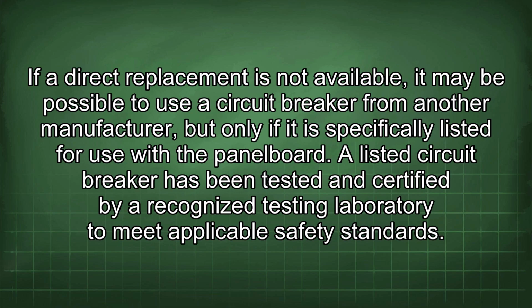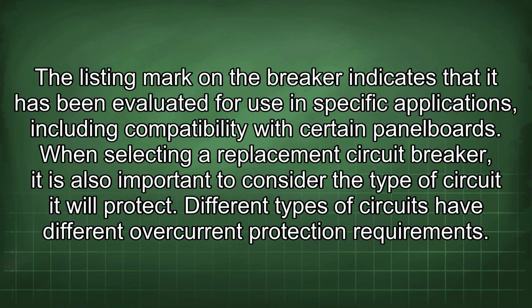If a direct replacement is not available, it may be possible to use a circuit breaker from another manufacturer, but only if it is specifically listed for use with the panel board. A listed circuit breaker has been tested and certified by a recognized testing laboratory to meet applicable safety standards. The listing mark on the breaker indicates that it has been evaluated for use in specific applications, including compatibility with certain panel boards.